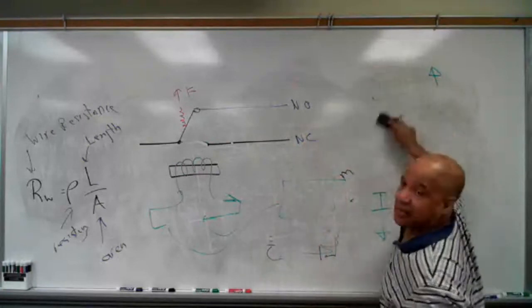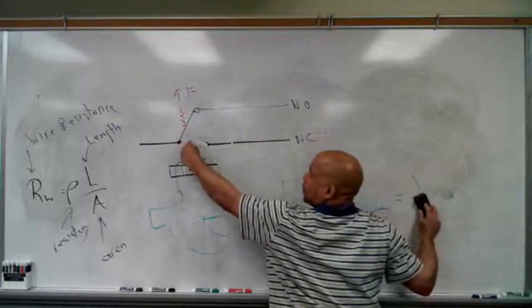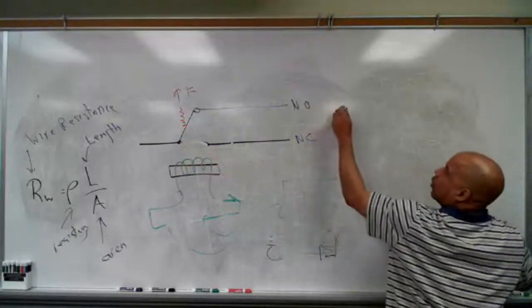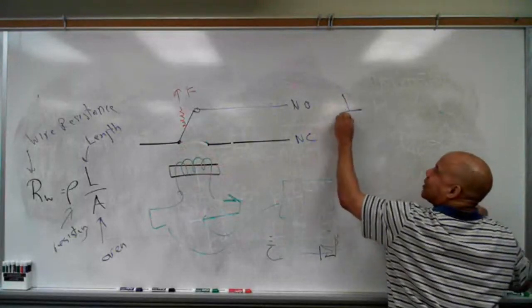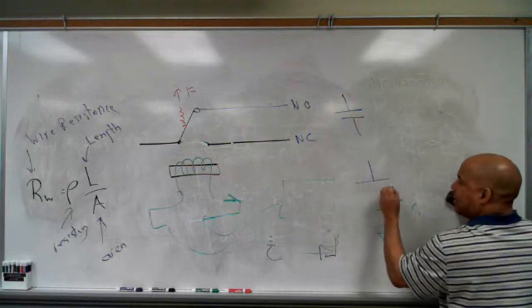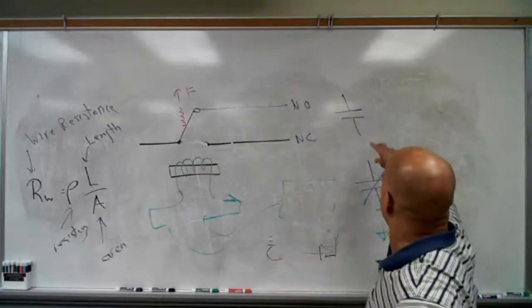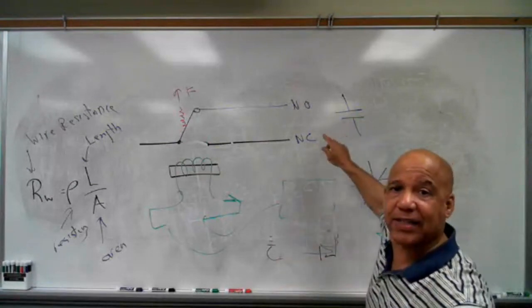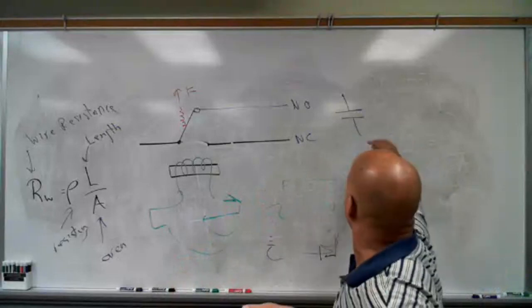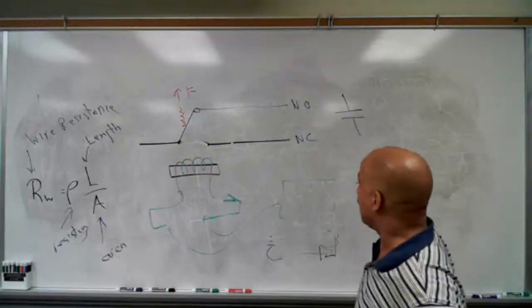And the way we represent this, and this is the last thing I'll say, Instead of showing the switch like this, we'll show a normally open contact like this. And this normally closed contact will show like that. And then in the next class, when we have more time, we'll build those AND, OR, NOT logics. Instead of using switches, we'll use inputs, represented by these relay contacts.